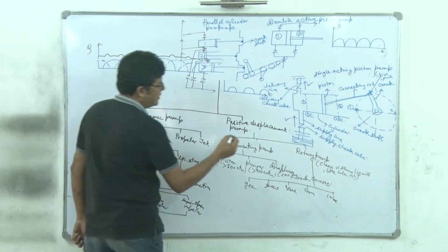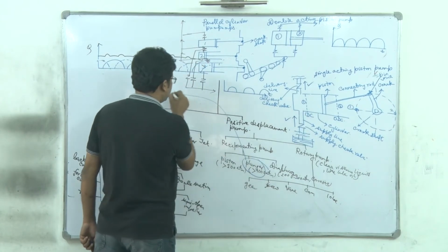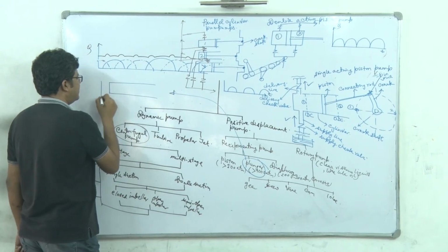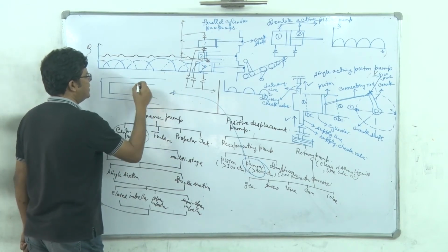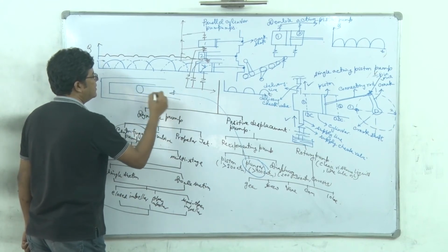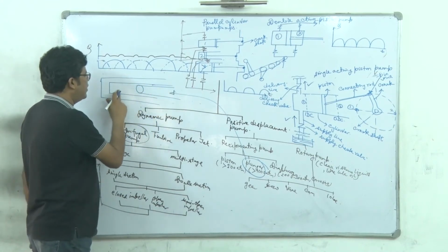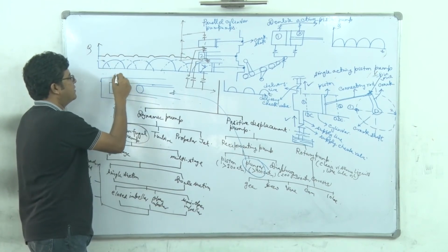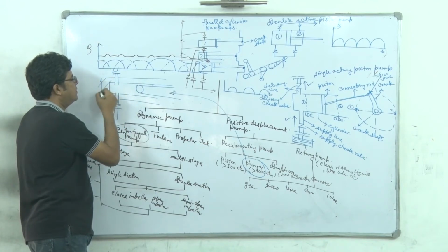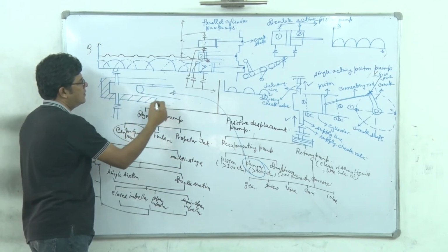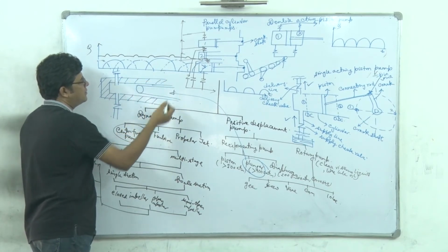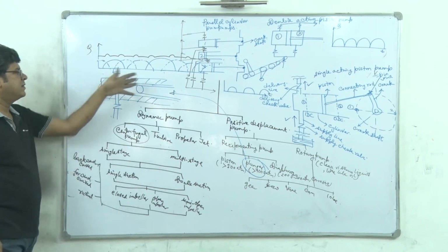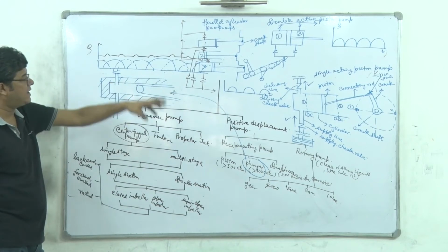So plunger is something where we have the bore itself. It's a thick walled cylinder, and there the plunger, meaning here the piston rod, simply reciprocates. And here we have this suction line and this delivery line. Right? So this arrangement must be extremely leak proof. Otherwise, as it is operating at a very high pressure, there is every chance that you will have leakage.